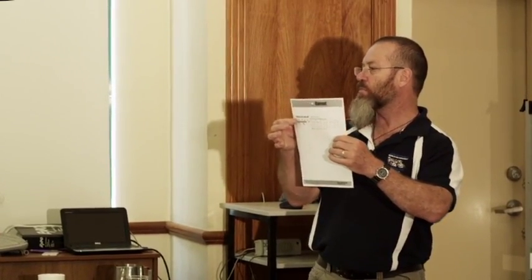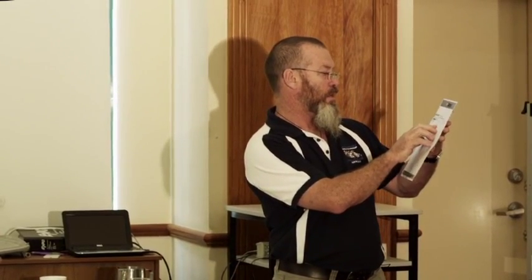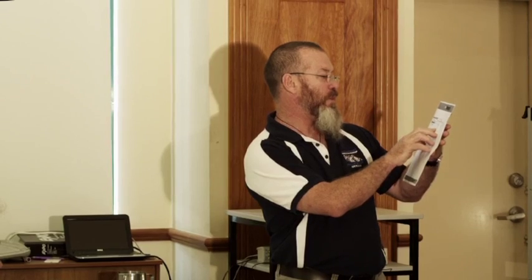Anchor bolts, have you seen these ones? Screw bolts, I call them. Ramset calls them anchor bolts. M10, they've got to be 50 millimetres into the concrete, M12 has to be 60 mil, so you're going to have a bolt that's like that. It doesn't give you edge depth, unfortunately. Oh, yes, it does. It's got to be 80 mil in from the edge. Can't use it. So you can't use anchor screws. So really, if you add all this information up, the only thing you can use along your slab edge is ChemSets.